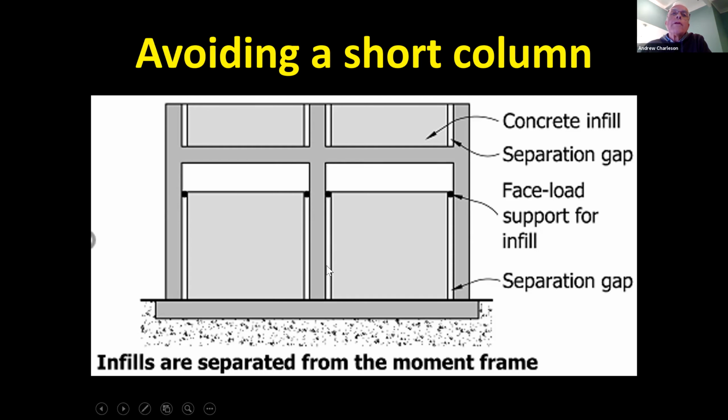You require them to be filled with soft material that will squeeze as the column bends over towards the wall. And then you need a sealant or metal flashings to create a nice finish over the gap. Of course, the sealant is soft, compressible sealant.